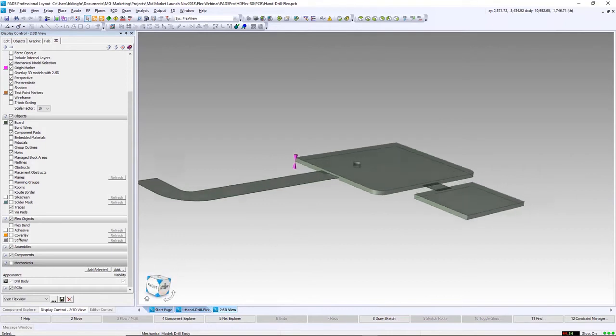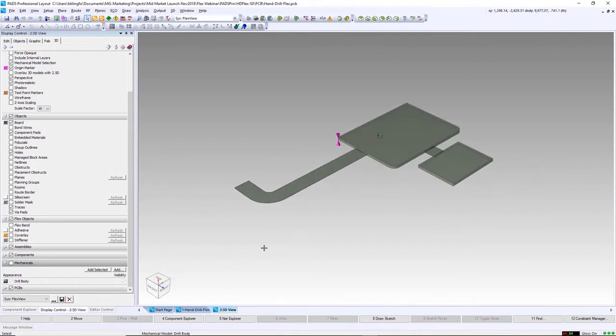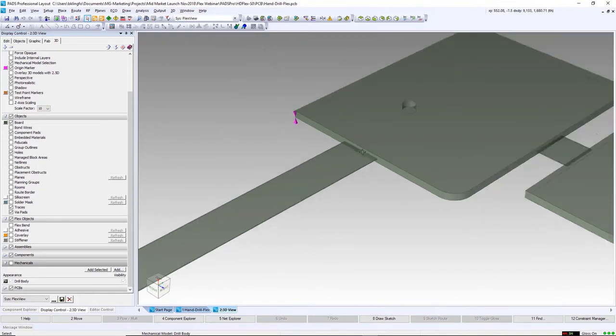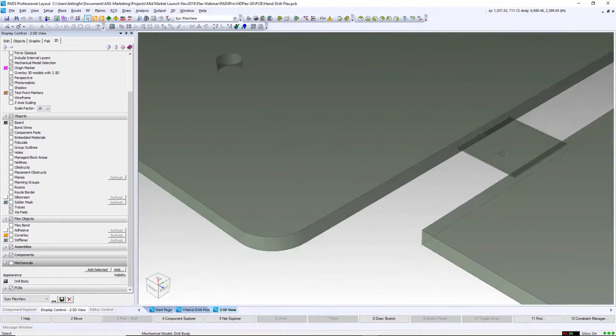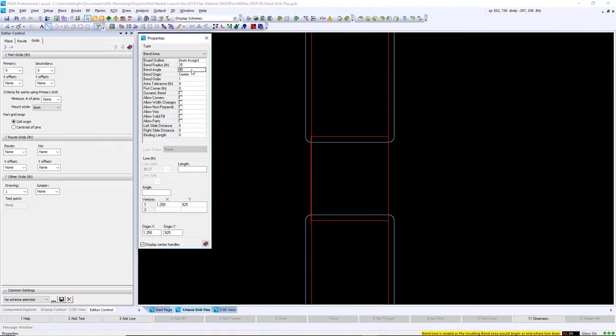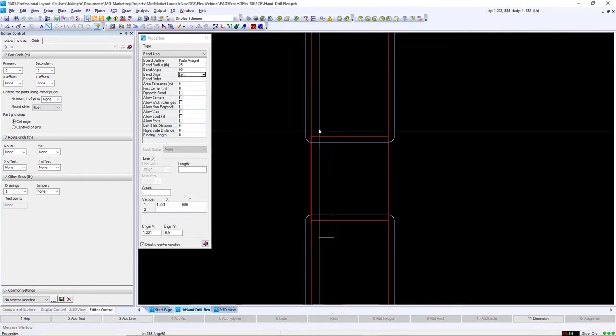While in this view, we will also notice the layer thickness for each region has now adjusted based on the stack-up assigned to that region. Now that we have board areas assigned to stack-up regions, we need to create the bend areas. Bend area definition is the second most important feature available in a modern ECAD tool when working with flexible PCBs.